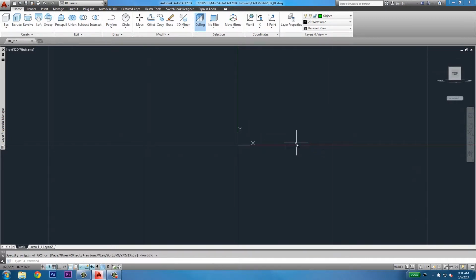You'll notice your view cube now says Top, not Front. That's okay. Up to the left, you'll see that you're indeed still in the front view. The next step is to draw the front profile of the object. Select Polyline from the Draw tool set, or type PL.